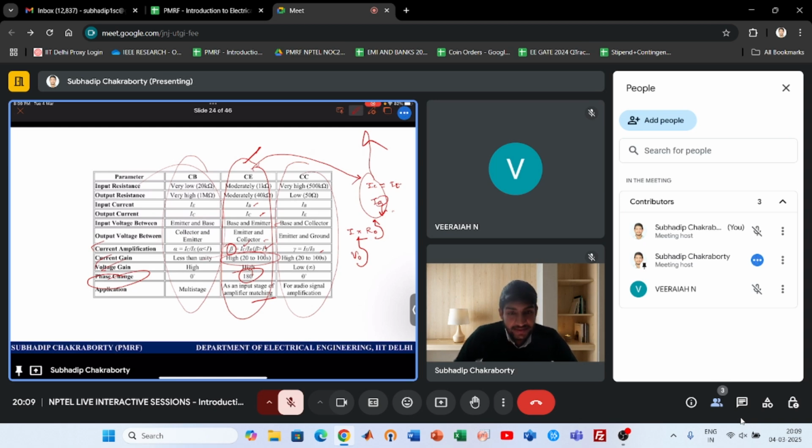The common emitter is much used in amplifiers, but the role or zone of operation of the device will be governed by the choice of biasing resistances other than the biasing voltages. So both the mode of operation you select, declared by the application of specific voltages at the emitter, base and collector leads, and alongside the choice of the biasing resistances and biasing voltage values, equivalently decide the zone of operation as well as the mode of operation of the BJT.